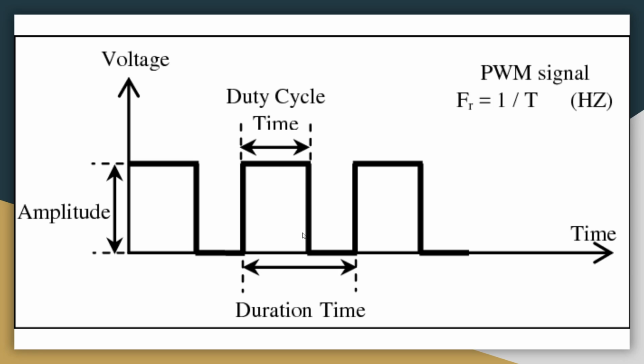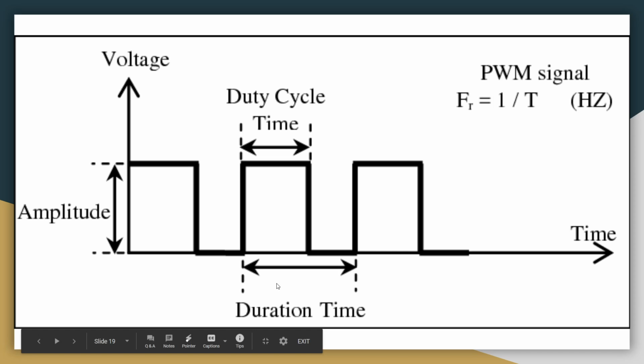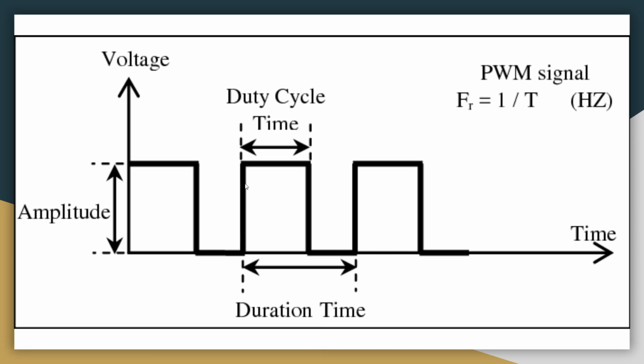You should remember that the time taken between switching it on and switching it on once again is a constant time. Okay, so this is basically called the time period, and this is a single cycle of the PWM operation. One cycle is switching it on, switching it off, and switching it on once again, and this time is going to be constant throughout the switching operation.